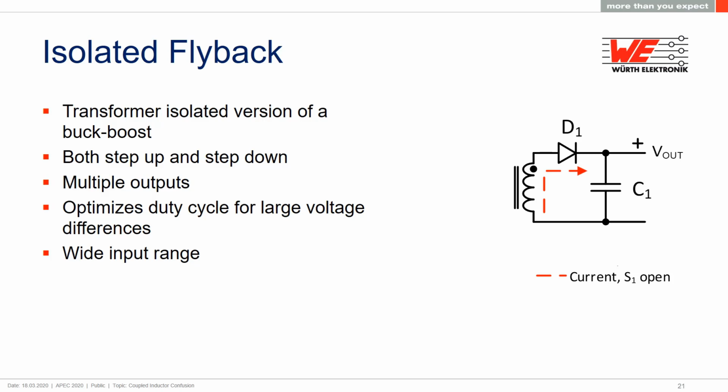Unlike a transformer, which strictly outputs to the turns ratio, a flyback's coupled inductor actually decouples the output winding from the turns ratio because they operate as independent inductors during their portion of the power cycle. I hope that doesn't add to the confusion, but think it through.